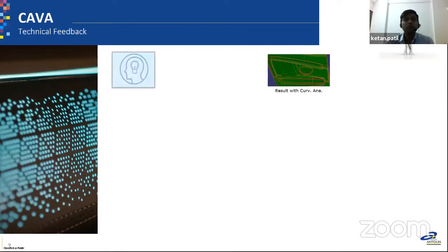Additionally, we were looking at the same time for a tool to optimize the result and reduce the time for manual checks, because while doing the manual checks we observed some problems which are not very critical. Curvature analysis was showing us all the results, or we can say all the radii which are less than whatever settings we are keeping, irrespective of whether this area is contactable by the sphere, as the regulation asks to check.